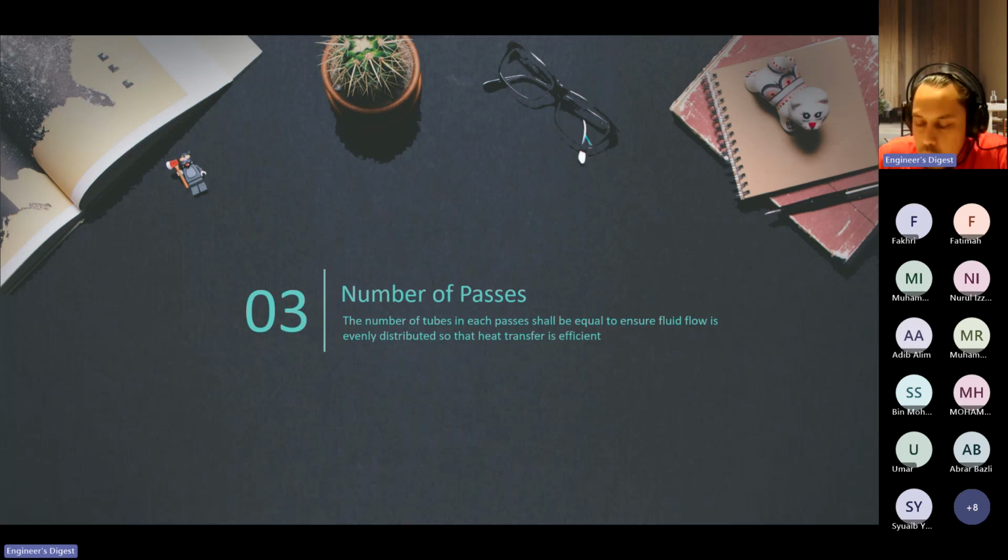or PED, because the process team can either run a simulation, or they can check through the PI trending. The PI trending means they will be able to monitor the outlet temperature, the inlet temperature, the delta T, and then make some calculation, and then say whether the heat duty is still okay or not.